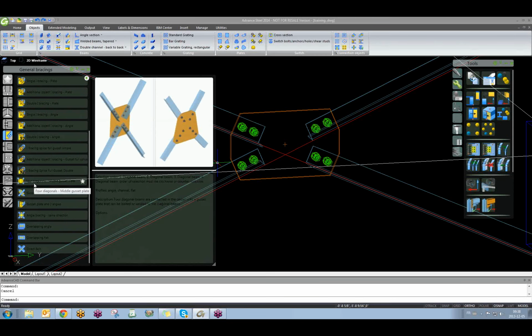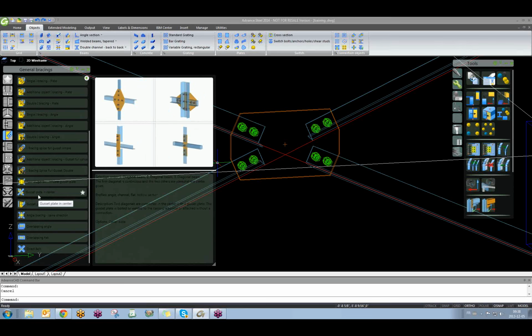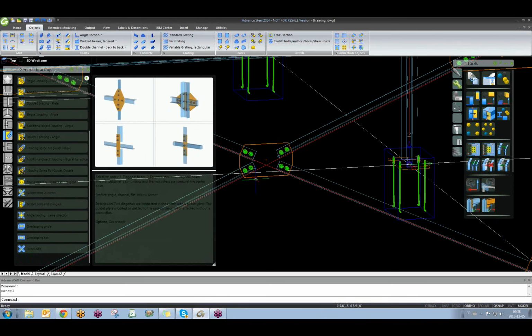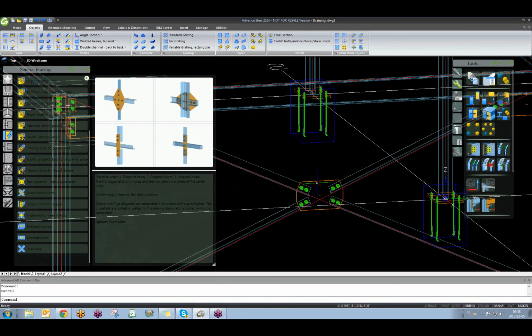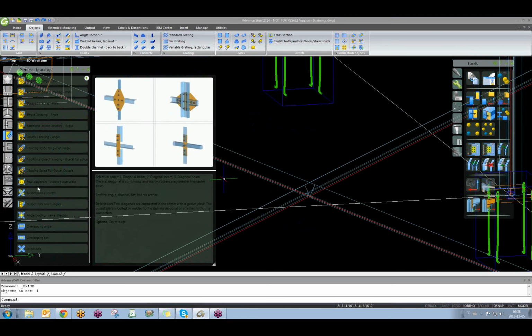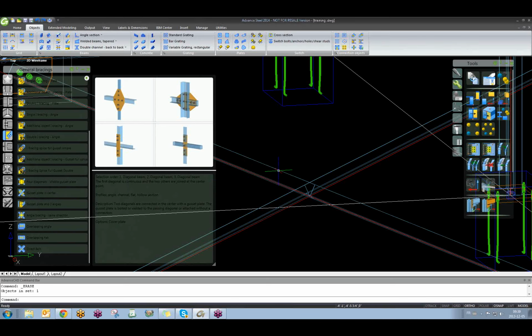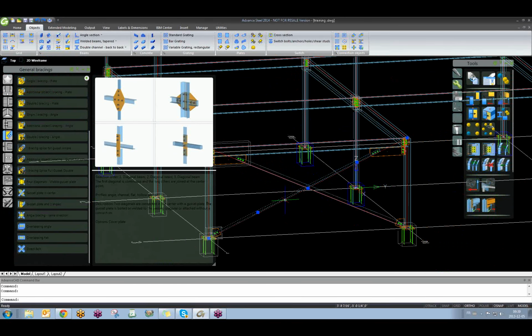the diagonal for with middle gusset. In here we have gusset plate in center. I will delete this one. Okay, I'm gonna delete it. So I will have this situation. For the gusset plate in center, we only need 3 beams as it's shown in here. One is split, but the other one goes through the plate. So I will have to merge one of the 2 beams in here.